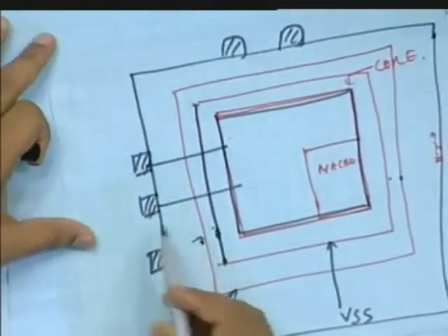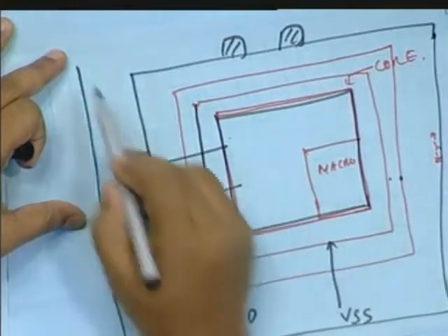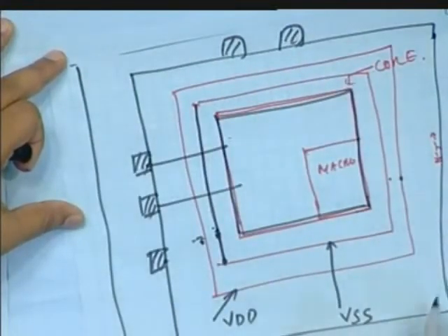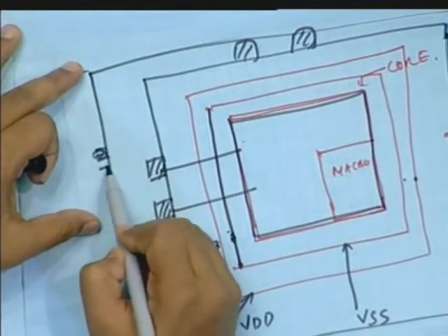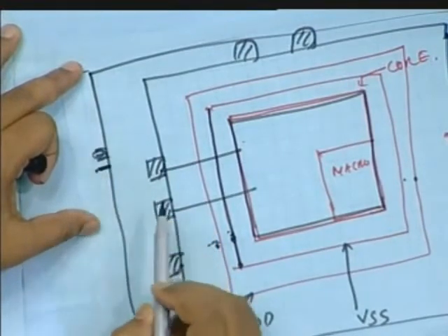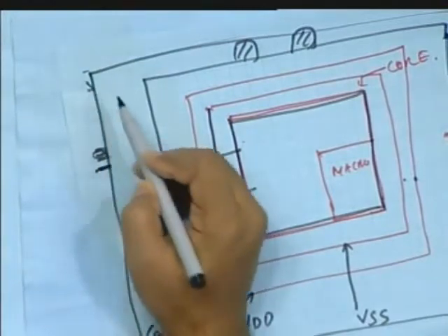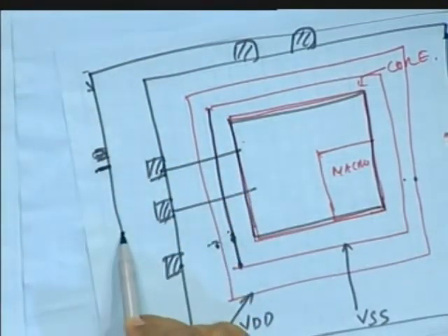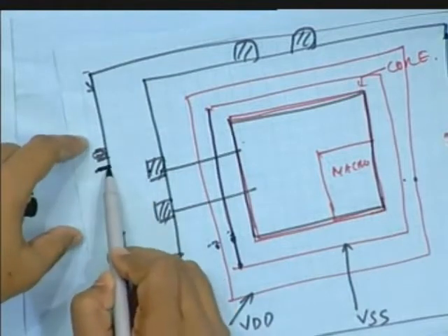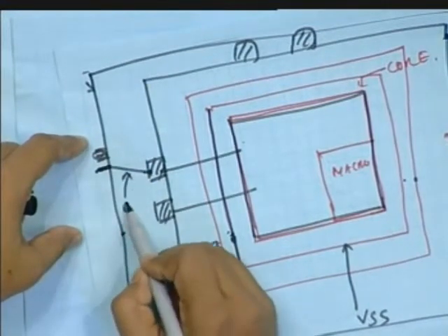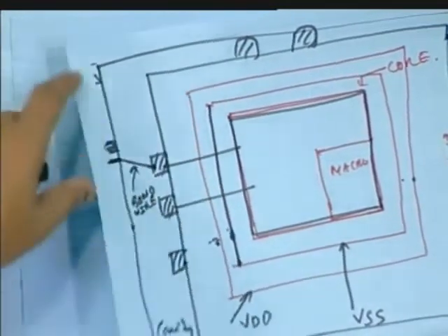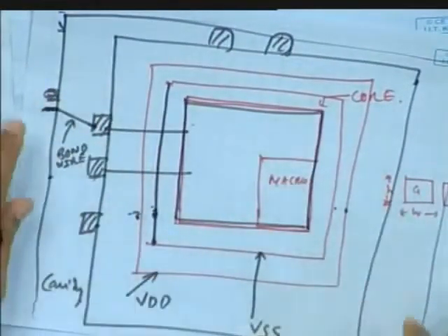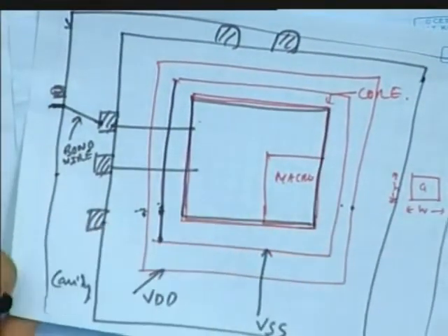Now there is a cavity after this. I am not drawing the right side, it's the same all around. This is called the cavity, and then your pin will be there, with pin inductance. So this is my package, the leftmost boundary is my package. From the pin to the pad there is a connection called a bond wire. So this is the overall look of any chip.